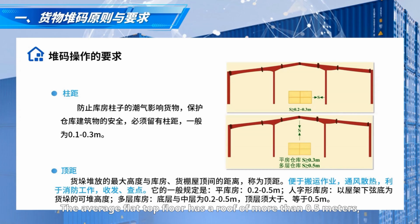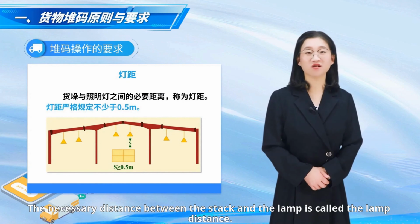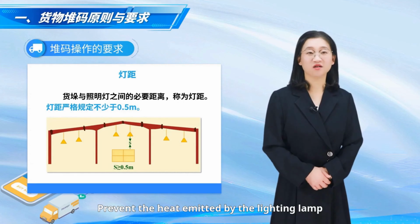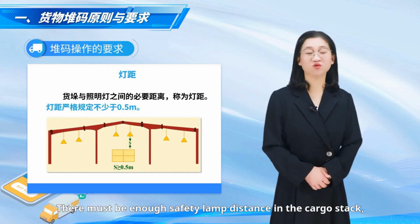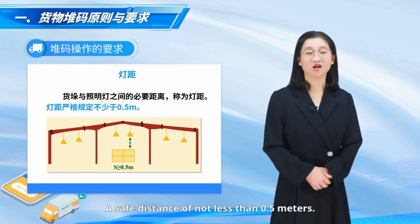The average flat top floor has a top distance of more than 0.5 meters; for the herringbone roof, the top surface of the stacking shall not exceed the beam. The last one is the lamp distance. The necessary distance between the stack and the lamp is called the lamp distance. In order to ensure the safety of stored goods, and prevent the heat emitted by the lighting lamp from causing a fire near the burning of goods, there must be enough safety lamp distance in the cargo stack. According to regulation, the safe distance is not less than 0.5 meters.